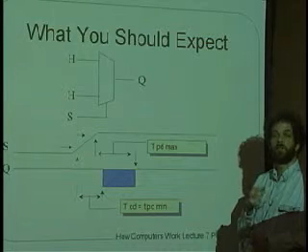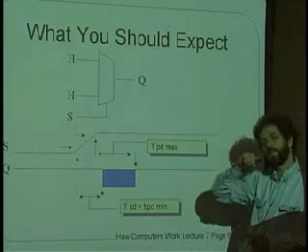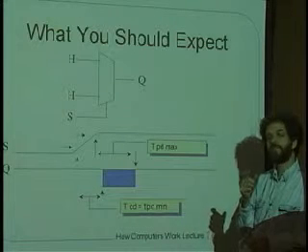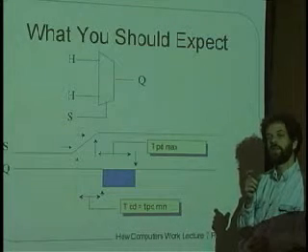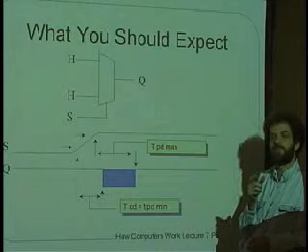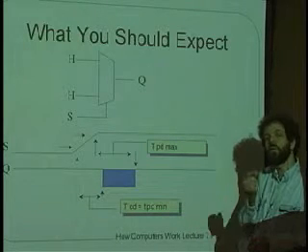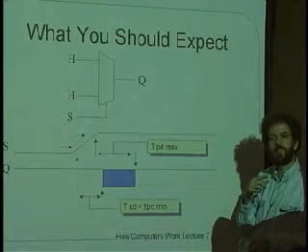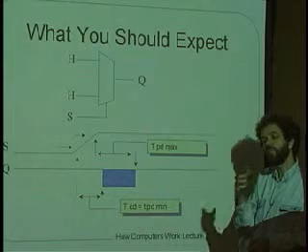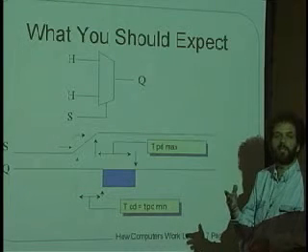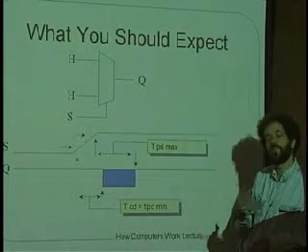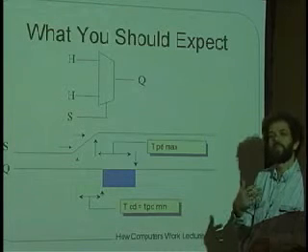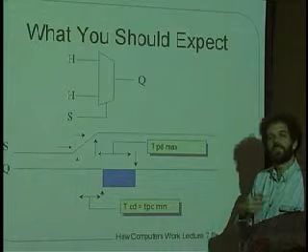too fast. Do you remember the hold time thing, right? We don't want the contamination to race around the loop before the hold time is up. So circuit designers in general worry about, will the contamination get to me too soon? And so the question is, what's the smallest amount of time for the contamination to start to race around the loop? One could say, what is the maximum amount of time too? One could measure that. But in general, it's not a measure that's very useful. What we care about mostly is how quickly will we lose the old data going around the loop.